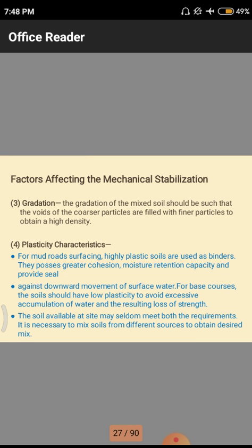in a very thorough manner. That means we have to mix those materials plenty of times, a number of times. Why? Because the existing soil has a huge amount of voids, so whenever we add another material from another land, automatically that material will have a binding capacity with the surrounding soil, then only we will get a good strength parameter. Next one, physical characteristics.